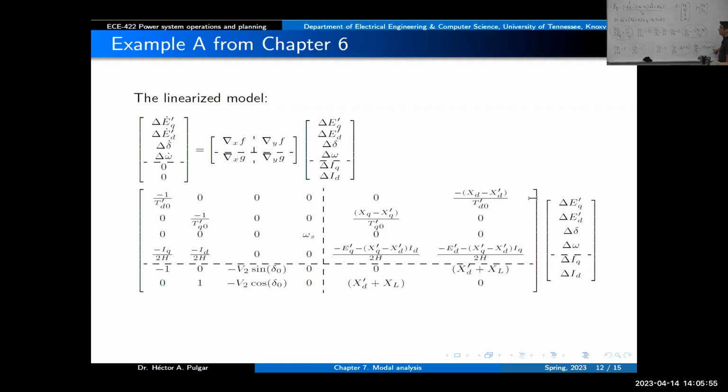So this is delta 0. With the speed is 0. The derivative with respect to IQ is this one over there. And I forgot to write it down with respect to ID, which is 0 because this equation does not depend on ID. So we will proceed in the same fashion with the other equations until you get all the Jacobian for the system.